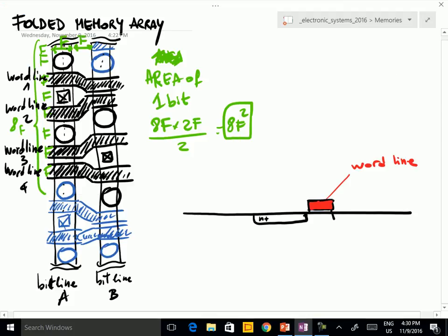And then here we have the source, which is N+, connected to the capacitor. The capacitor has this shape, goes below, as there is a drill. This is drilled in the MOSFET, and essentially there is this N+ region here, which is one electrode of the capacitance.